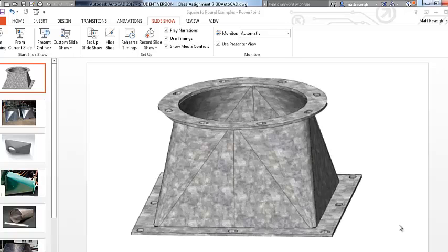So now we move on and pick up on some new developments, squared arounds, which fall into a category called triangulation developments. So we're going to use Pythagorean theorem a lot here to define true length. So I just want to do this as a setup video for squared arounds, and then we'll get into our next class assignment, which I'm thinking I'm calling class assignment 7, is going to be an actual squared around.